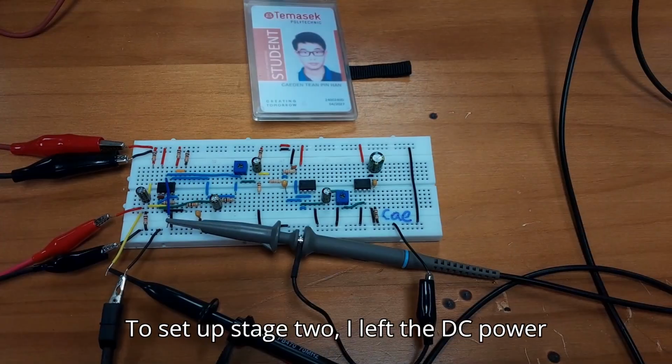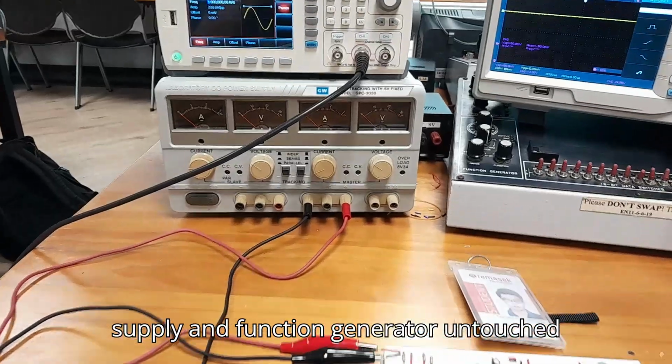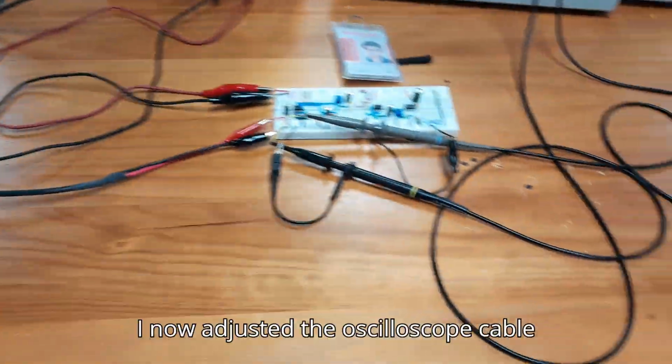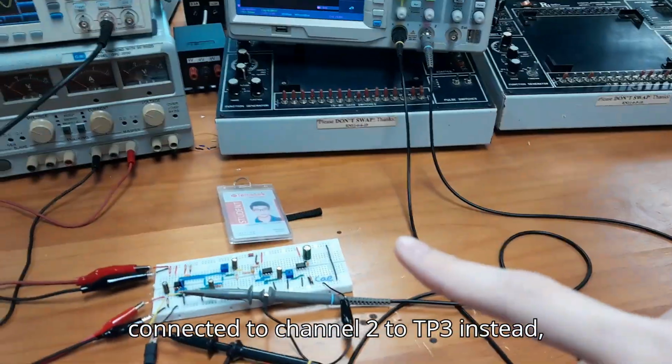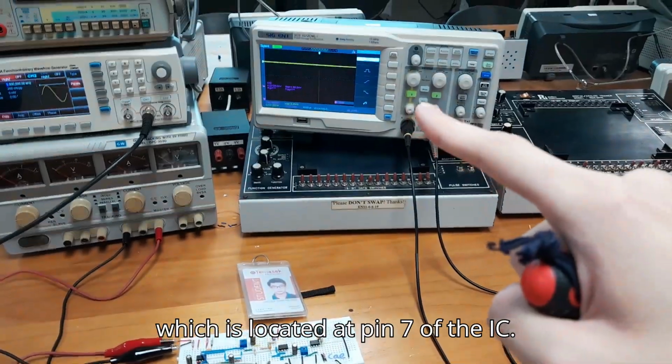To set up stage 2, I left the DC power supply and function generator untouched and did not change any values. However, I now adjusted the oscilloscope cable connected to channel 2 to TP3 instead, which is located at pin 7 of the IC.